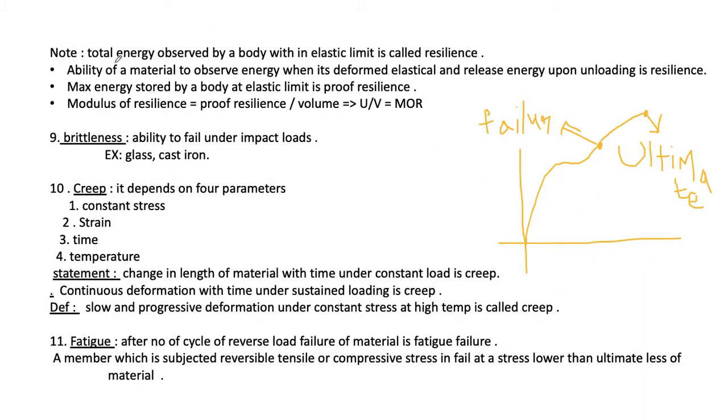Next, note point. Total energy absorbed by a body within the elastic limit is called resilience. This is the elastic limit. In the red mark, I am showing the stress strain curve up to the elastic limit of mild steel, which is nothing but resilience. The total energy is absorbed by a body within the elastic limit only. Within only the elastic limit, the energy is totally absorbed. The ability of a material to absorb energy while deforming elastically and release energy upon unloading is resilience.